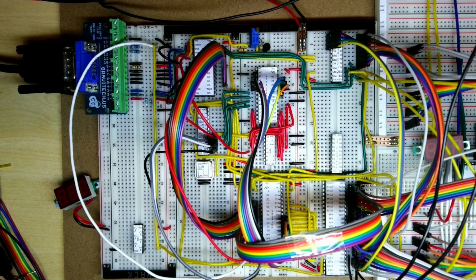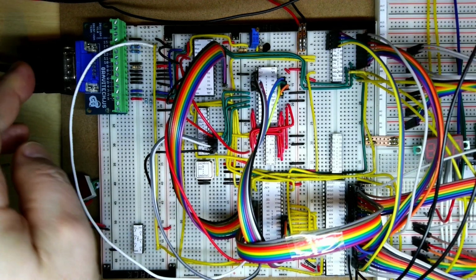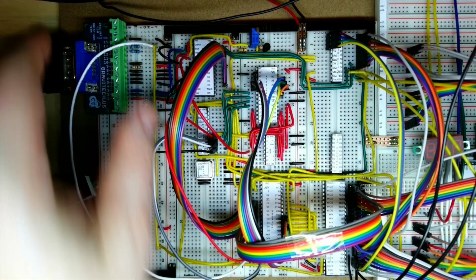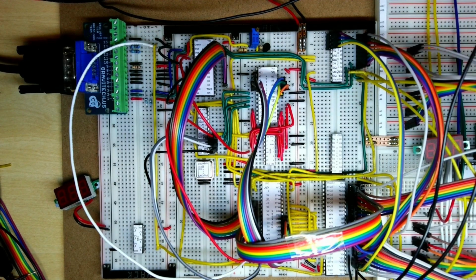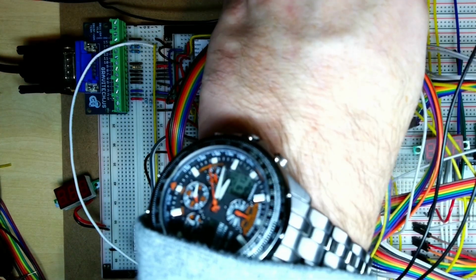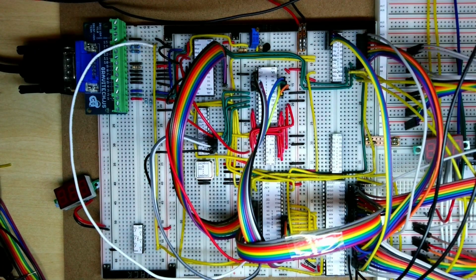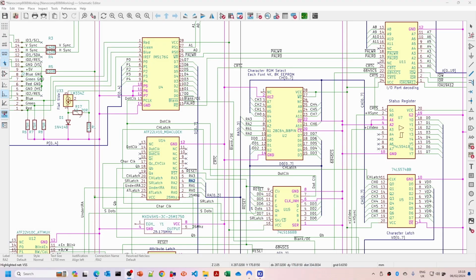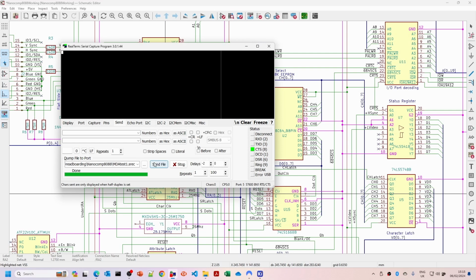That should mean we're only going to be using the 0 and 1 palette entry. So just going to plug in the serial cable, plugged in the video capture, VGA capture card. So we just need to now download a test program. To start with, I'm just going to download the black and white test 1, so MDA test 1. Okay, so powered on the nanocomp, we're just going to send the first test program down, which will probably do grey and black. So I've put the nanocomp into load, send file, so that's downloaded, and then when we start this, we'll just go to the screen share.